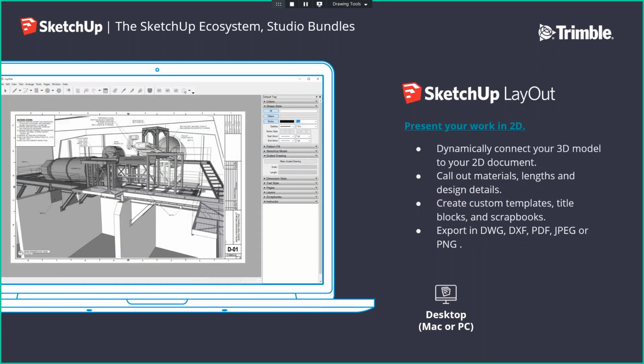SketchUp Layout is where you can present your 3D models directly into a 2D space. So now you can connect dynamically your 3D model to your 2D documentations. You can call out materials, lengths, design details. If you require to create custom templates, you also can do so in Layout. And you can export this in DWG, DXF, PDF, or the image standards, JPEG and PNG.